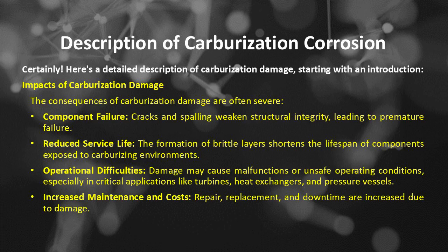Number 2 is reduced service life. The formation of brittle layers shortens the lifespan of components exposed to carburizing environments. Number 3 is operational difficulties. Damage may cause malfunctions or unsafe operating conditions, especially in critical applications like turbines, heat exchangers, and pressure vessels. And number 4 is increased maintenance and costs. Repair, replacement, and downtime are increased due to damage.